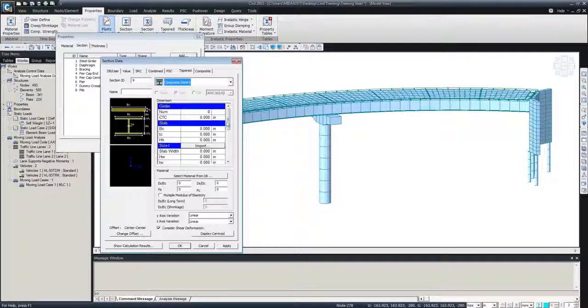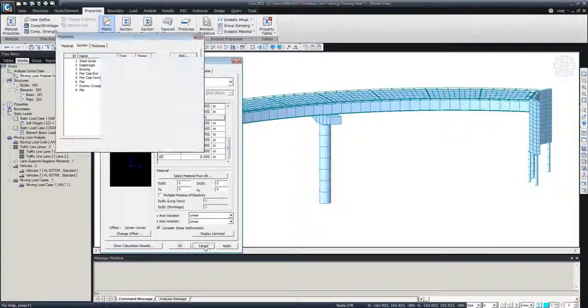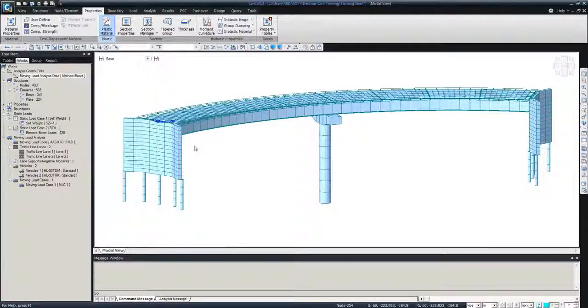Let's say steel I girder. So here for the I end we have the slab width, and for the J end we have slab width as well. But probably this is not satisfying what you are looking for, Andrew. But probably we should define different slab widths for different parts of the bridge. That will be the best way, I think.